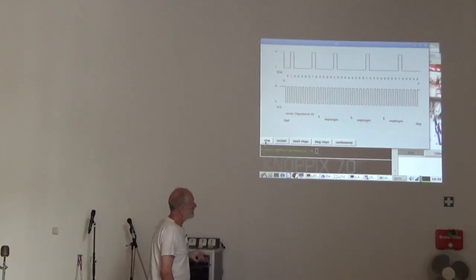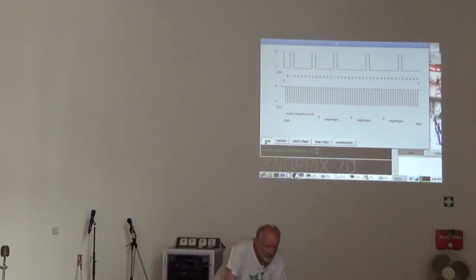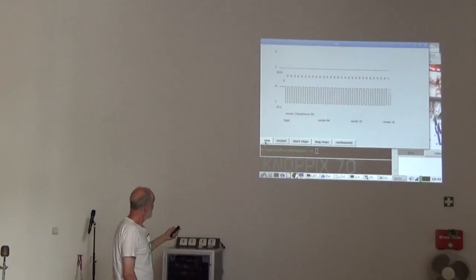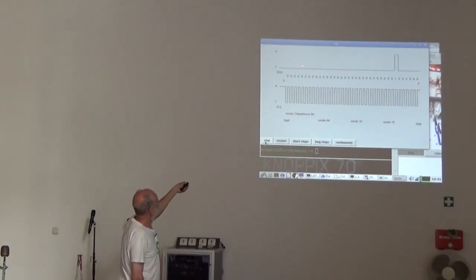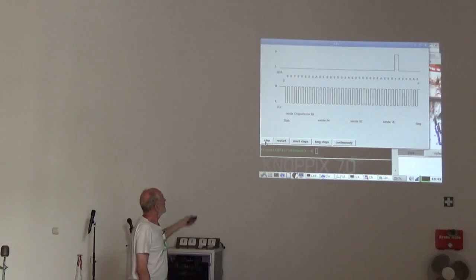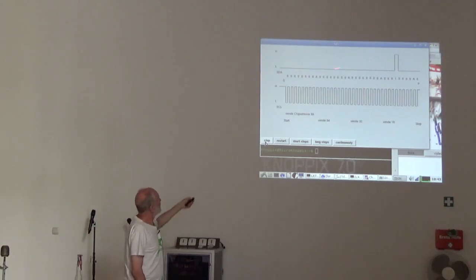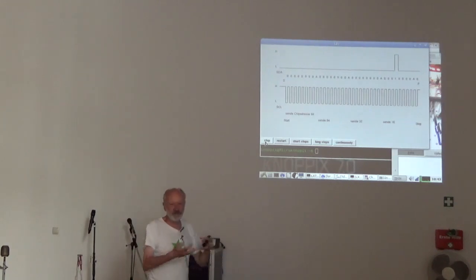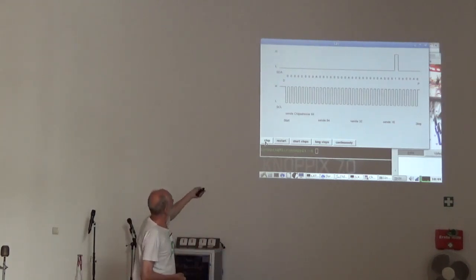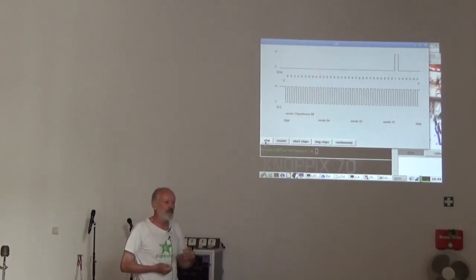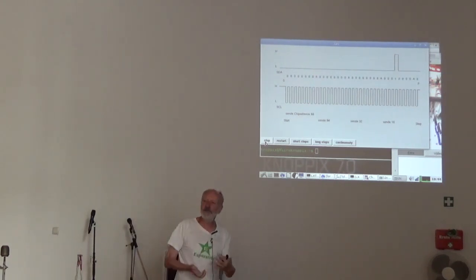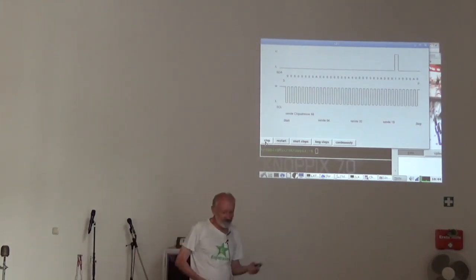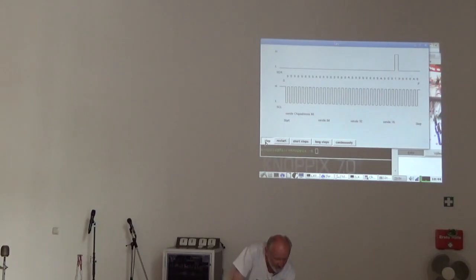And when I continue, I get nonsense on the bus because the line is always low, and the chip thinks it shall send data. It sends the data and acknowledges it, but it's not that I start a new communication. So it's not the right thing.